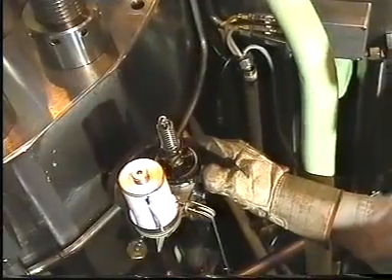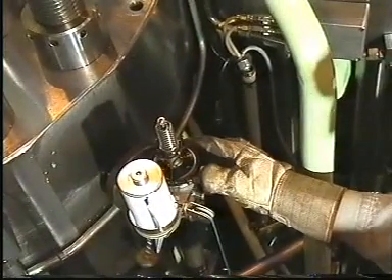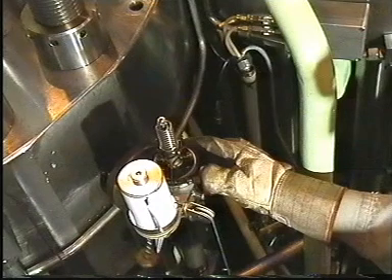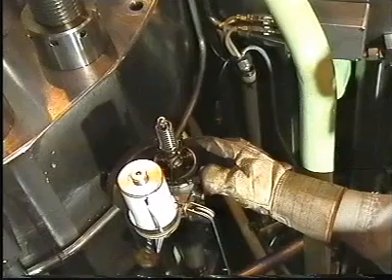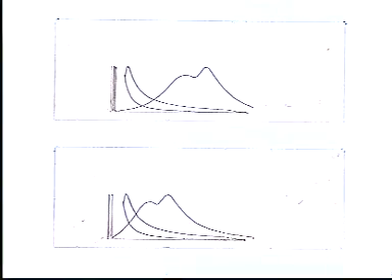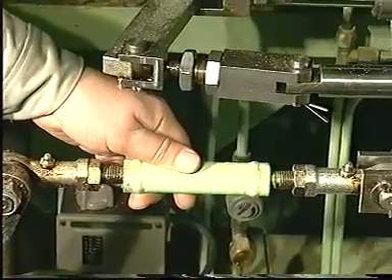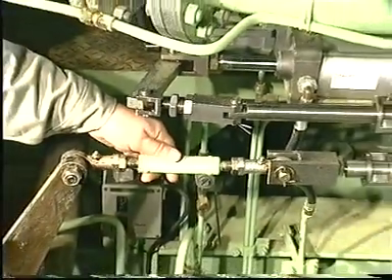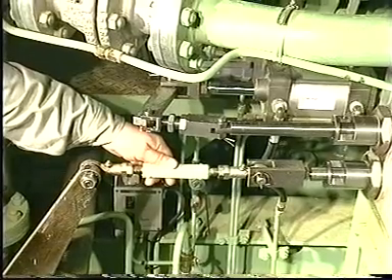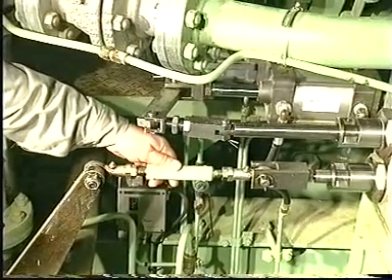Use the indicator drive or PMI system to adjust the load so that it corresponds to the breakpoint load and 100% MCR load. Note down the fuel pump indexes. The mean indicated pressure of the individual cylinders must not deviate more than 0.5 bar. If the deviation is larger than 0.5 bar, adjust the load distribution on the fuel index rack of the individual cylinders.